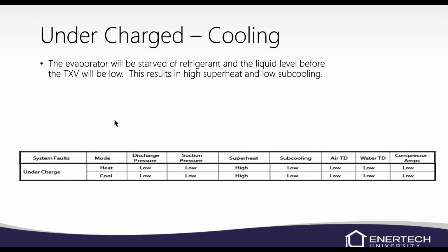Your evaporator will be starved of refrigerant, and the liquid level before the TXV is going to be low. It's going to result in high superheat and low subcooling. Normally, it will not freeze up the entire coil either. You'll have some ribbons of frost maybe.